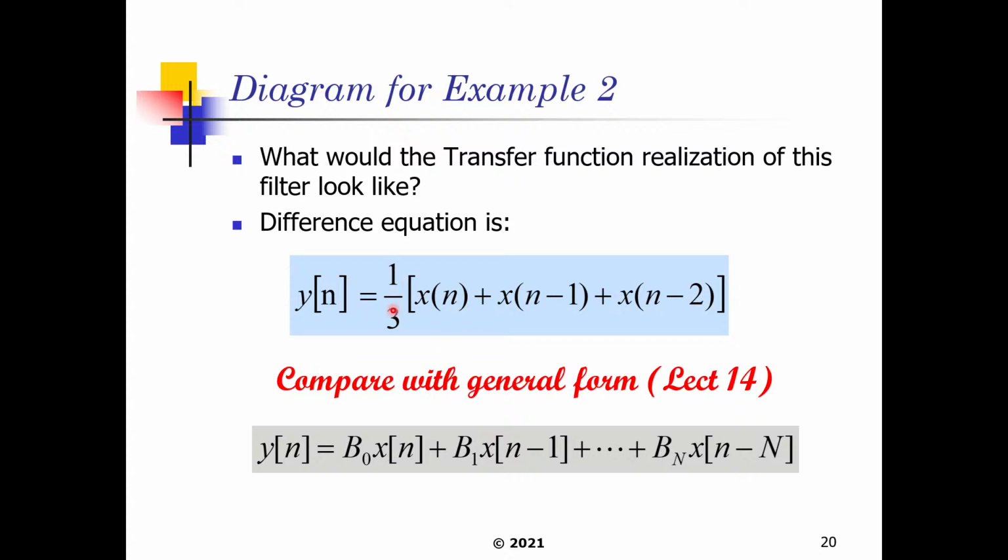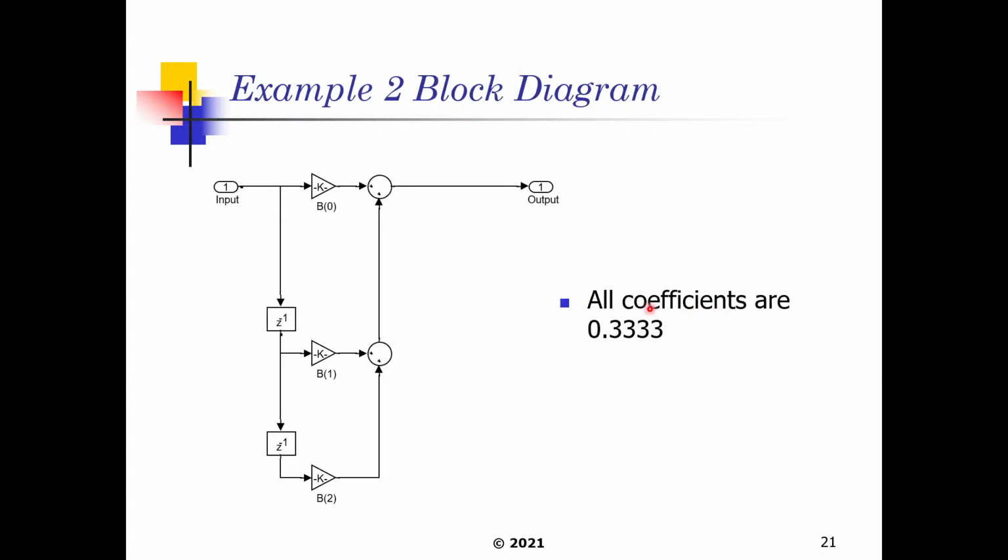So for our filter design here, this 1/3 is going to multiply by each one of the delayed signals there, being x of n minus 1, x of n minus 2. So this 1/3 here for each one of these triangular blocks is going to be mapped onto these triangular blocks here. And remember, this here is basically our x of n, which is basically 1. X of n minus 1 is matching to z to the negative 1. And then our x of n minus 2 is z to the minus 2 here accordingly. And this filter design is a feed-forward system.